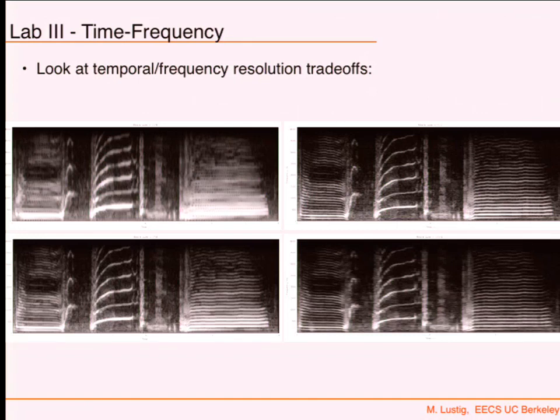If you sample at 2.4 megasamples per second, and you're recording 10 seconds, that's already 24 megabytes. No, more. It's 24 times at least 4. But it's complex data, so times 8. So it's like a 100 megabyte data set that you're going to be operating on. And that's for just 10 seconds. So efficient computation is really important.